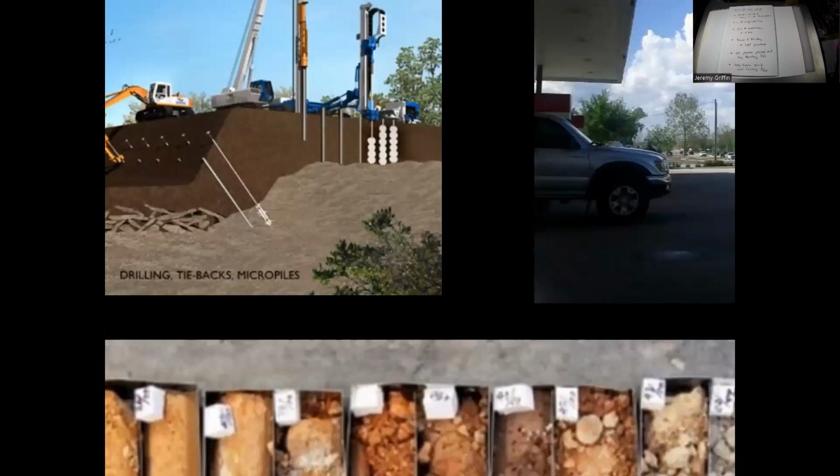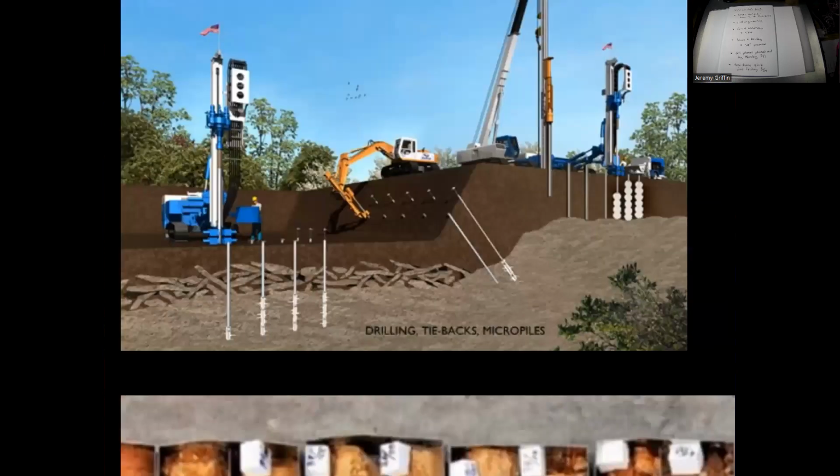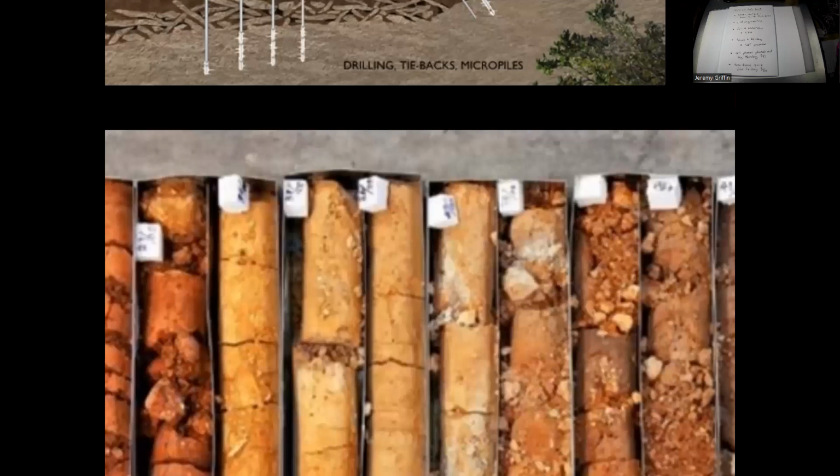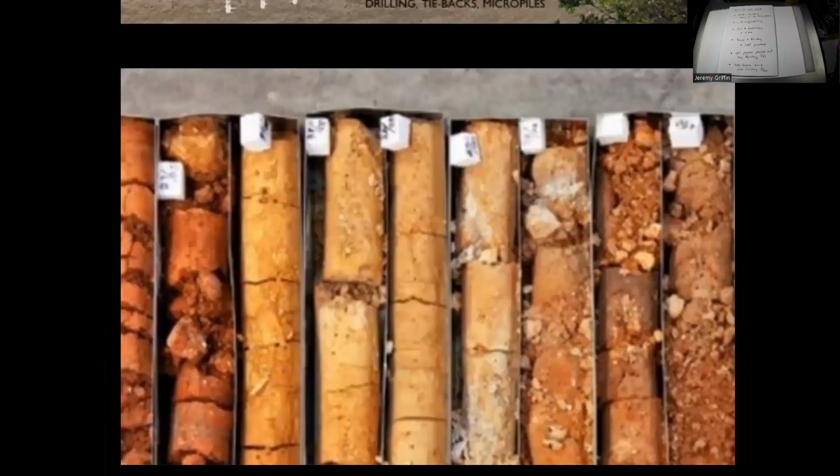So how do you do that? Well, before the construction project begins, you go to the land and you drill down and you get these core samples. These are what these core samples look like. And that's how they know, like, so many meters down, we got this type of clay, and so many meters down, we got the sand, and so many meters down, we got this bedrock, right? Or I guess you could also bounce sound waves off too.